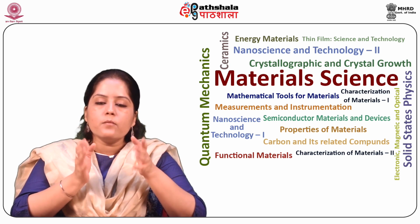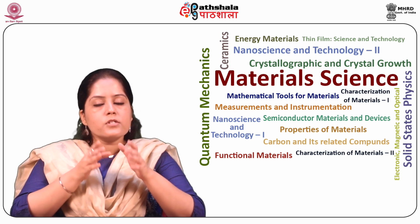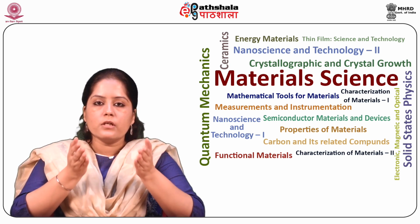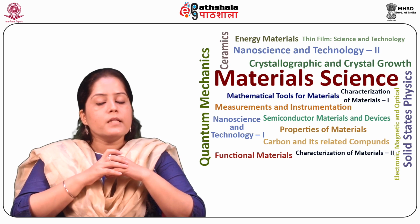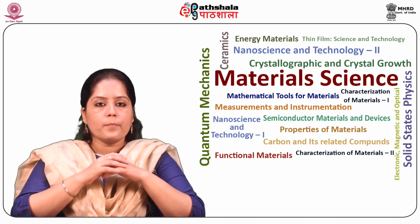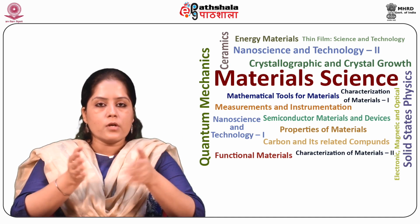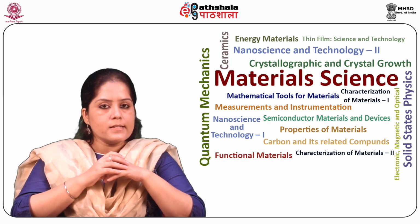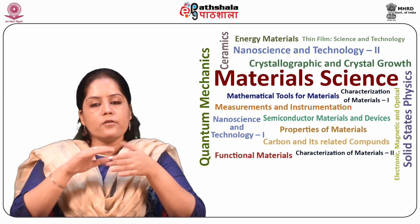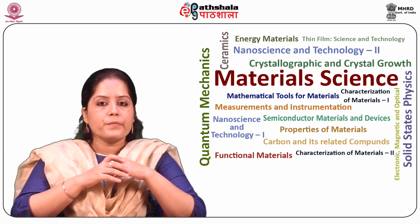Now, what is the importance of the oxide? In the CMOS transistor, the oxide is an essential component. In the gate, it is called gate oxide. Thus, it is the essential part of the structure. Second, it is used for protecting the silicon surface. Thus, it's a passivation layer.